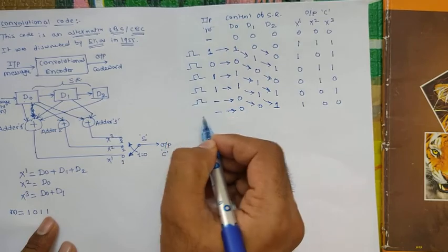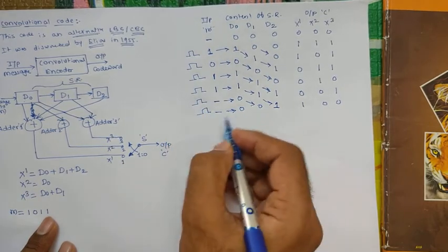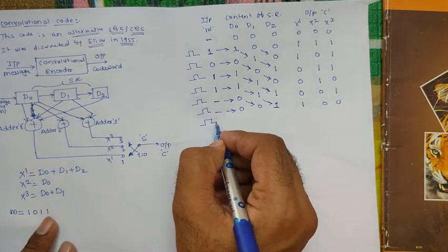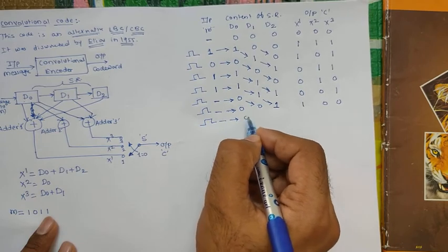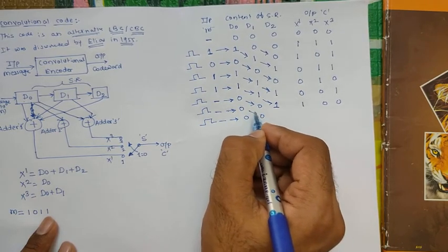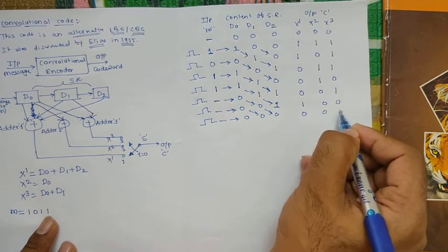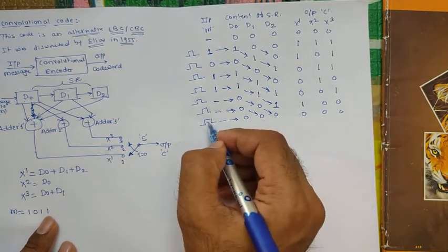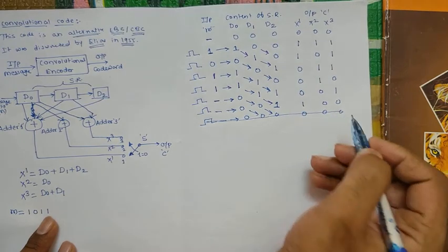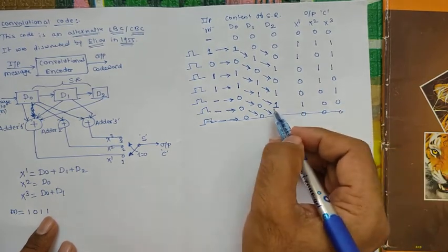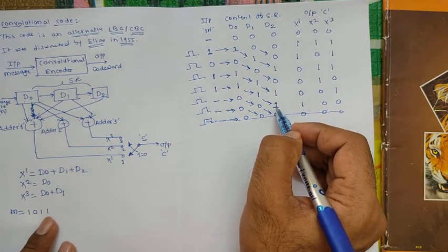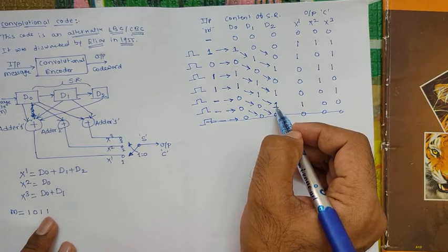So this clock cycle is very important. When we apply the next clock cycle, since nothing is there, obviously this 0 will be here, this 0 will be here, so no input means we are not getting any output. So there is no meaning in looking at this particular thing. Our operation is only valid up to the last input bit reaching the last shift register.